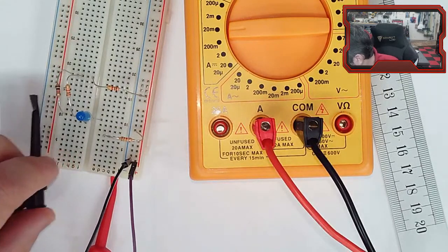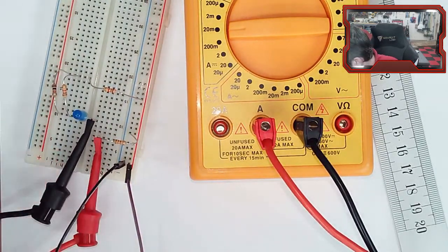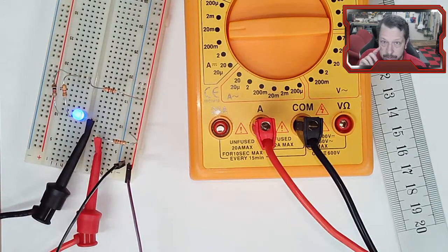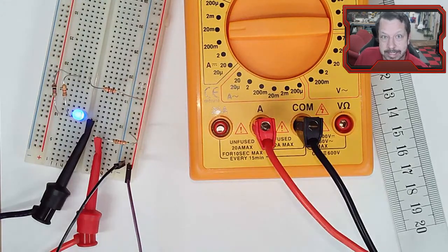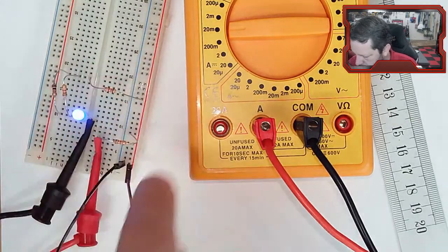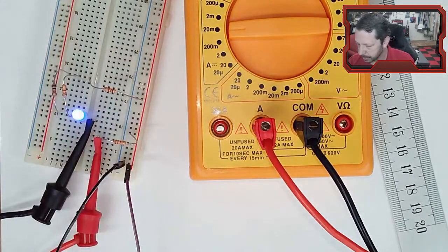All right, let's turn our voltage back down and see if that does any better. There we go. So LEDs, if you don't remember, are biased. The D part in LED is a diode, and it only lets current flow in one direction, and I actually had it backwards. All right, so I'm applying 4.7 volts across here, so 4.7 volts in the entire circuit.